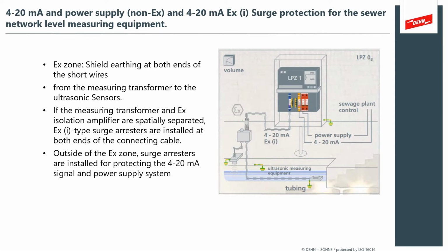In this slide, we're seeing an extended view of a very typical system, and the illustration really is helpful because it shows us all of the aspects that we've already been talking about. Your equipment is bonded, your remote metal, I like to use that term, floating metal, those elements are all bonded, and that controls the voltage across the metal components. And then you apply your surge protection to control the voltage across the electrical circuits. So what's nice about these diagrams, in one diagram, you have the opportunity to see many of the aspects of lightning protection that we've been discussing throughout our webinar series.